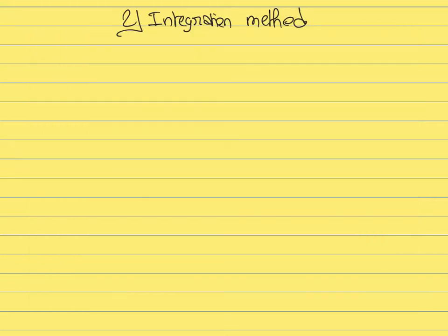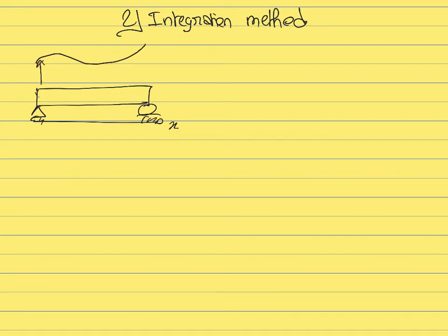To derive this integration method, we are going to consider a very general case, where you have a beam like this along a given axis X, and this beam can be attached to some supports, so some pins, some rollers, etc. The beam can also be subjected to some distributed load, W, that depends on X. In addition to that, you can have some concentrated forces, shear forces at a given position like this, or some concentrated moments, applied at a given point.